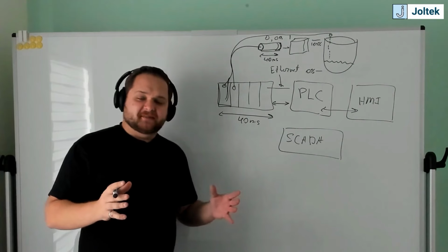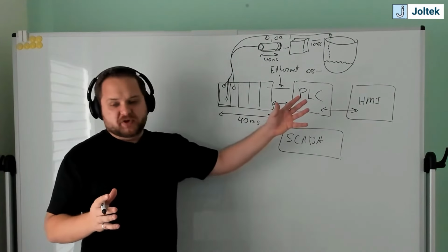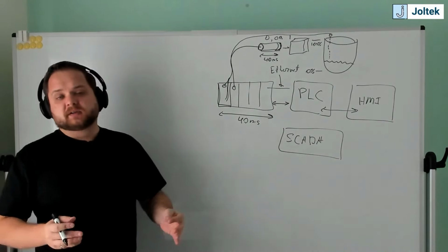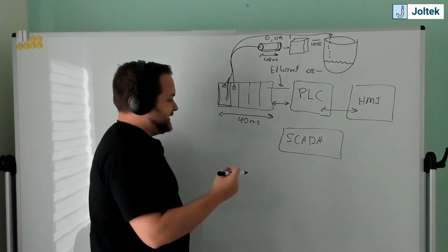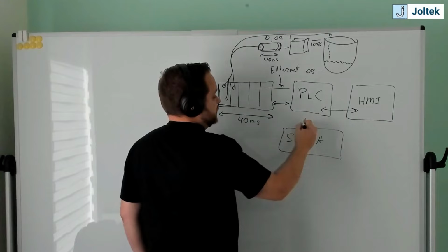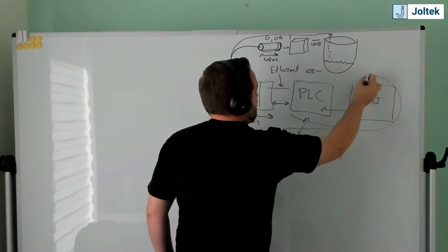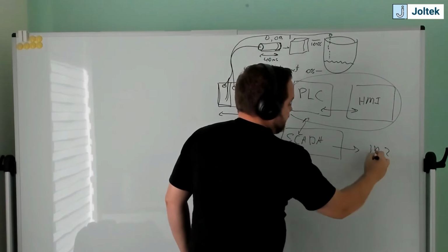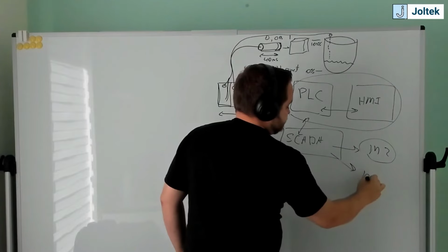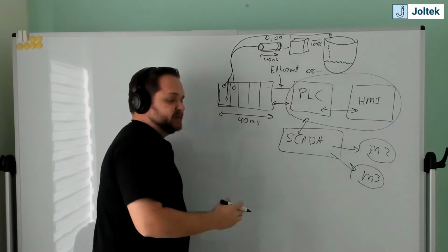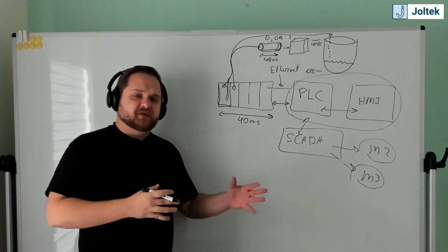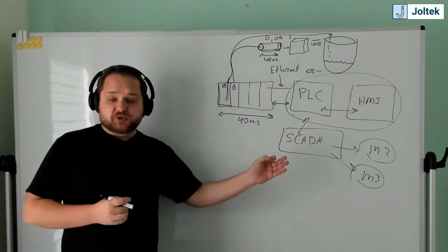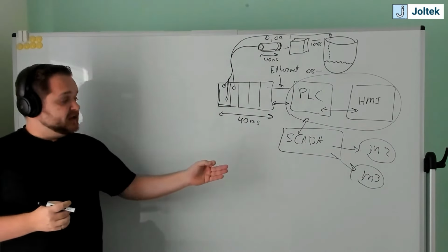Again, there's going to be some debate whether SCADA is part of HMI, or HMI is part of SCADA. But ultimately, what I want you to take away is that a SCADA is going to control multiple machines, right? So here, I'm going to draw this line. It's controlling this machine, it's controlling this machine 2, it's going to control machine 3, etc., etc. But ultimately, it supervises, and it also gives you some information as to how the system has been doing in the past, and that's going to be your SCADA platform.